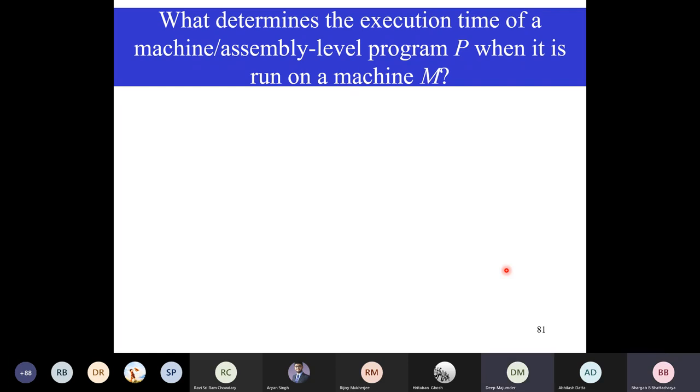The type of the instruction, like ALU instructions, probably take less time than load instructions, which access memory. Yeah, that is one issue, but we'll discuss that later, because if the time of instructions varies, then there may be difficulty in synchronizing the pipeline, right? Because you have to keep track, since it will be variable time instructions.